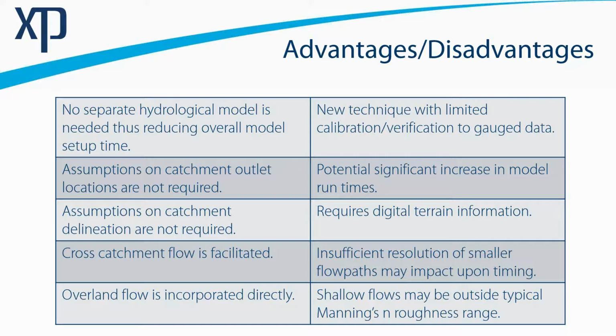But it is a new technique, as I've mentioned. There's only been limited calibration of this technique to gauge data, so having calibration data is very, very important if you have it, and to use that data to verify what you're doing. And that's the case with all hydraulic modelling or hydrologic modelling.